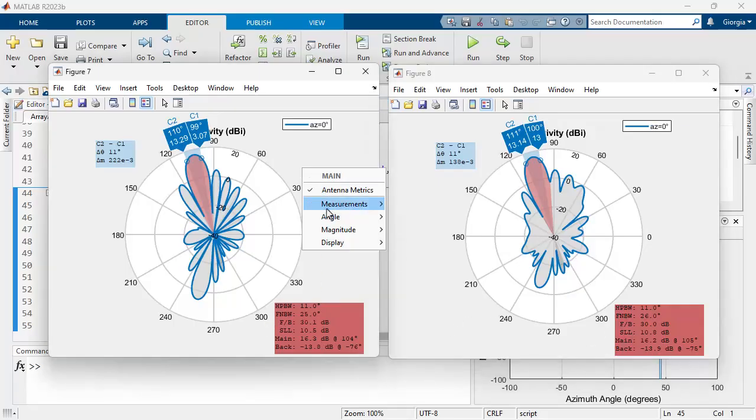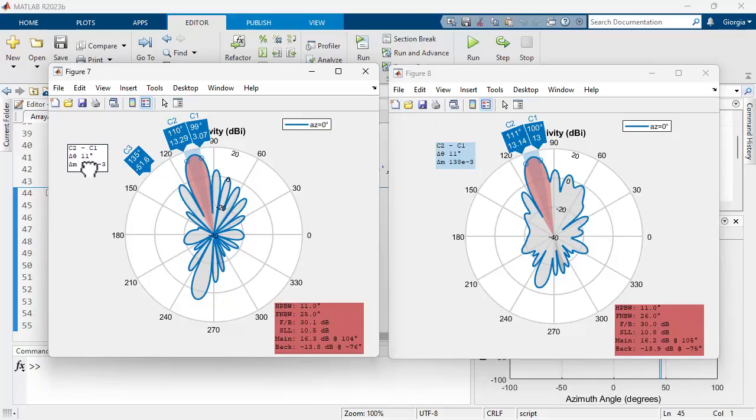our beam is steered in the right direction, but also that our null is indeed happening at 45 degrees from boresight. So here we are just adding, let me just add a cursor here. It's exactly 135 degrees, so 90 degrees plus 45 from the boresight. And you can see how without coupling, the null is much deeper compared to with coupling.